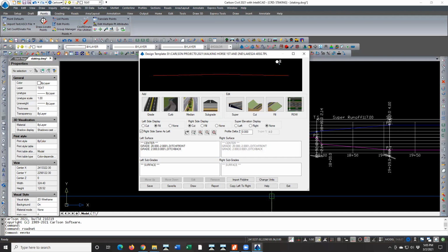Looks like you've got a 20-foot segment at a 2% down, and it's called the ditch front, which would basically be the edge of pavement, right? Well, like I said, this is subgrade, so okay. So this would actually be where the ballast, where we use a foot of ballast under everything out here. Okay. And so that's where my bottom rock would meet the ditch and then go up at 4:1 to get to the edge of the shoulder. Okay, so in a 2-foot ditch.